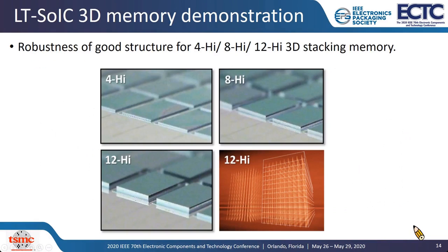Here, we show images of the 4-high, 8-high, and 12-high DRAM stacking made by low-temp SOIC, including a 3D X-ray image of the 12-high structure. This brings strong confidence that the robustness of low-temp SOIC technology has great potential to be applied to 3D memory, especially to HBM.